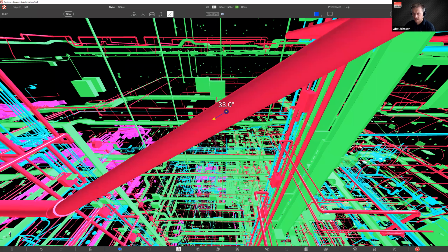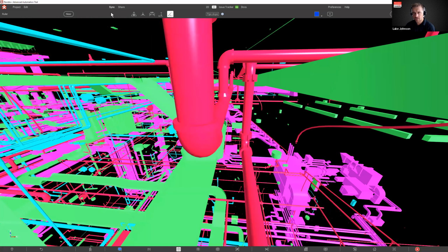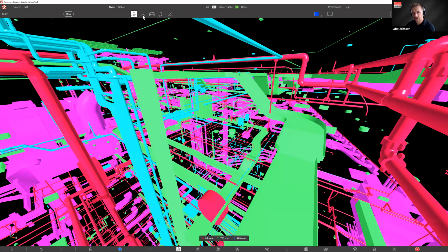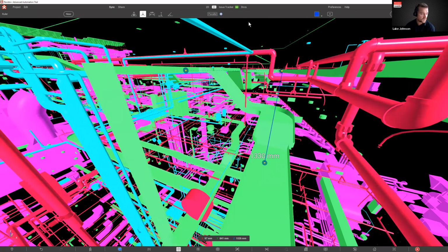We also released a host of other enhancements here in measuring. If we go to the normal measuring mode, in fact, point to point, when you make a point-to-point measurement, in the past it was just off on any kind of angle, whereas now you can go perpendicular or parallel, and you can drag the gizmo, choose the surface that you want to run perpendicular or parallel with when you're doing that dimension. So that's much more powerful for our measuring as well. At the bottom left of screen, you'll see now the little 3D widget, which helps you figure out which way is up if you ever get lost in your model.